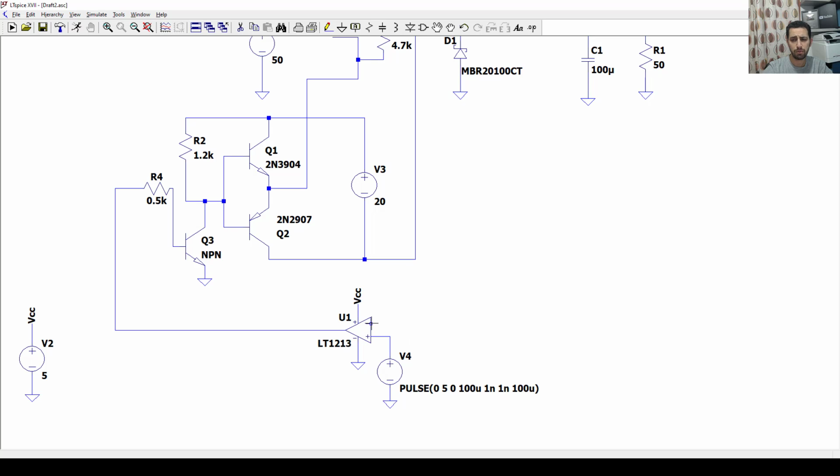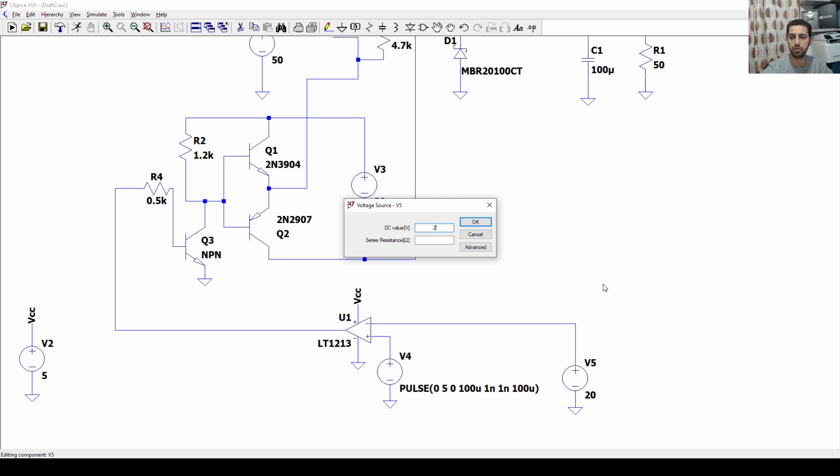Okay, now that source here, I can bring another source just to show you what I mean. This is my source, and here is a ground. Okay, and let's now just wire it and see what I mean. Now we have that comparator, which will compare that signal with a voltage. That voltage, I will choose it to be 2.5. Okay, 2.5 is a middle point between the 0 and 5. So there will be output on, off, on, off, on, off.